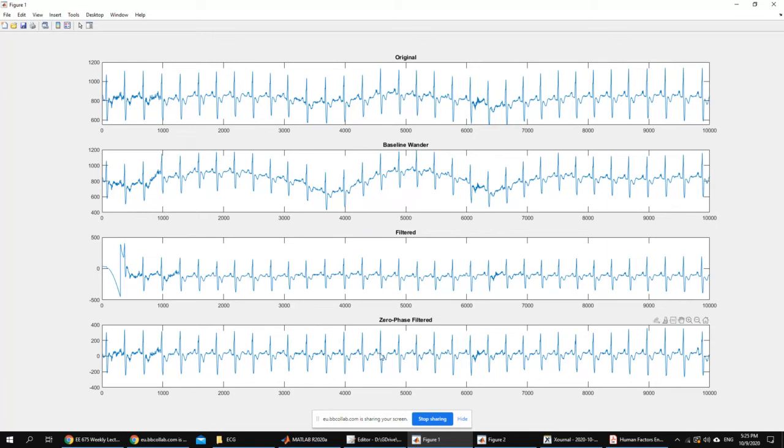If the zero phase filtered result gave you the minimum error, then using this filter in real time would be okay, because it's exactly the same filter, but removing the transient and the group delay. You understand what I mean?